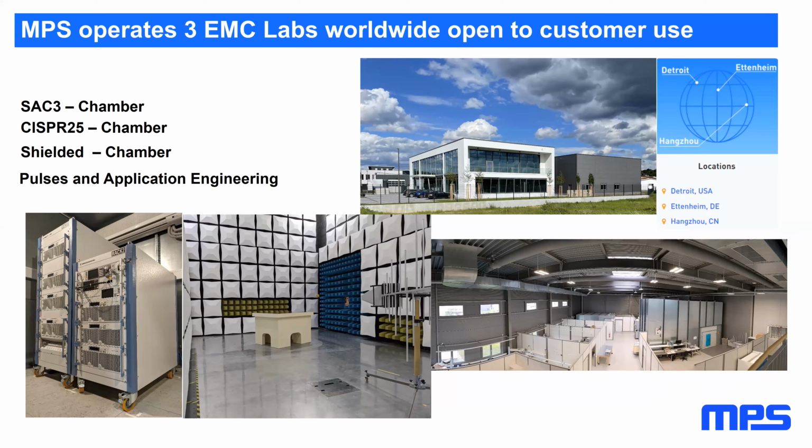The first one, I think you had an FAQ that sort of addressed this, but it's a statement here. Spread spectrum strategies have always struck me as a sort of trick aimed at complying with an arbitrary set of rules, passing whatever standard is being tested against, as opposed to considering whether the aggressor DUT is truly less offensive to victim devices.